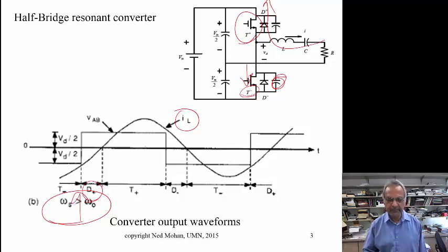So we essentially get a 0 voltage turn off because of these lossless snubbers, and we can afford to put these capacitive snubbers here because we see that turn on occurs at 0 voltage as well. So this is a circuit which is quite commonly used in various applications. One of them is ballasts of compact fluorescent lamps.